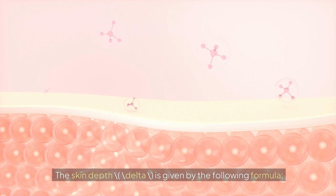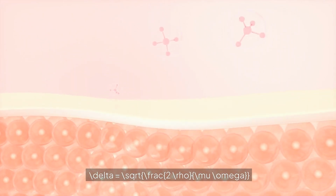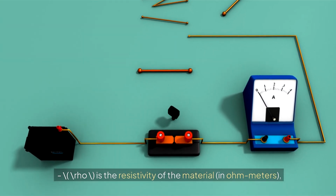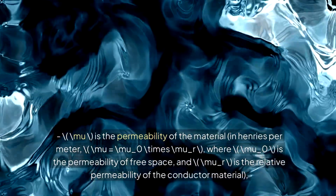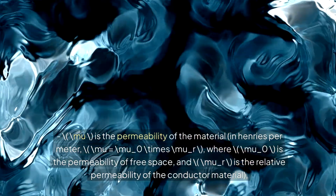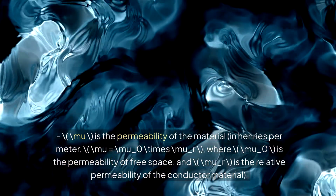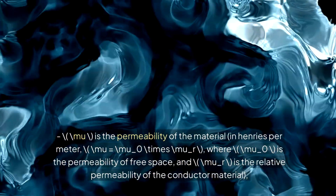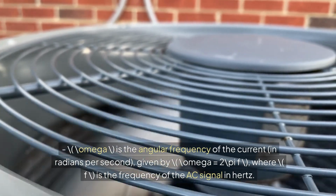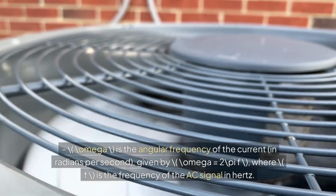The skin depth, δ, is given by the following formula: δ = √(2ρ/(ωμ)), where ρ is the resistivity of the material in ohm meters. μ is the permeability of the material in henries per meter. μ equals μ_0 times μ_r, where μ_0 is the permeability of free space, and μ_r is the relative permeability of the conductor material. ω is the angular frequency of the current, in radians per second, given by ω = 2πf, where f is the frequency of the AC signal in hertz.